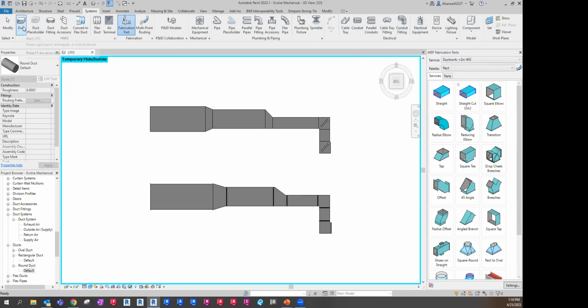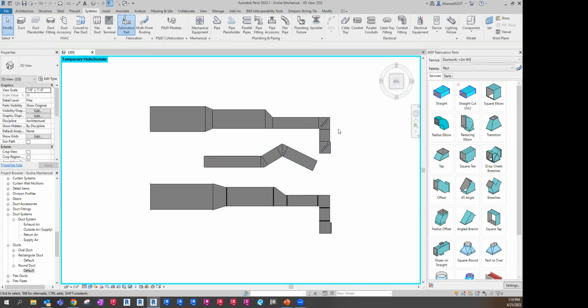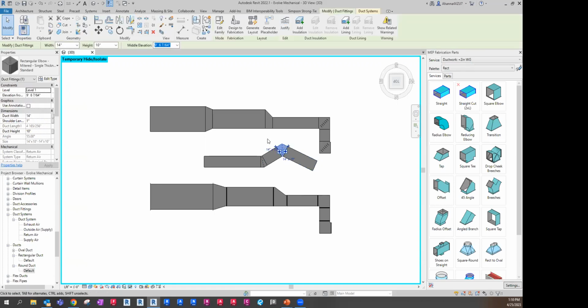In the HVAC panel, these are families. I can place a duct here. I can put a bend here and a bend here, right? Families are built to be placed easily within the model, but families built within Revit are also built based on calculations and equations. So not every piece that is built automatically through routing preferences can actually be fabricated. Like, parts don't actually exist. Some people don't fabricate their bends, they buy their bends, right?